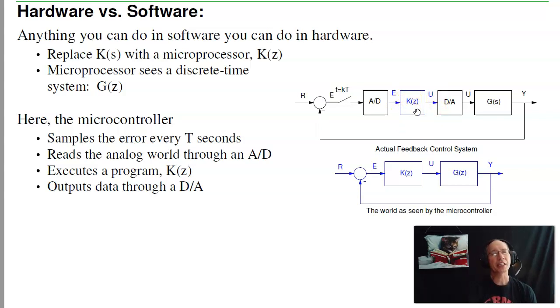And it's actually how most feedback controllers are implemented nowadays. Microprocessors are so small, so cheap, so powerful. This is a very good solution to many problems. The challenge, however, is since this is a microprocessor, you really need to analyze it in the Z-plane, not the Laplace plane. So the next couple lectures we'll look at how you design feedback controllers in the Z-plane.